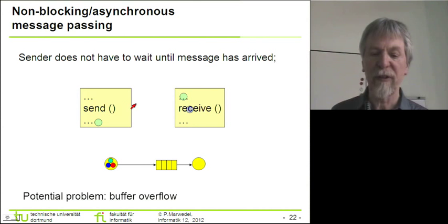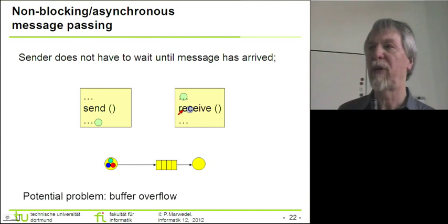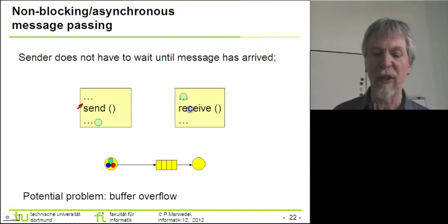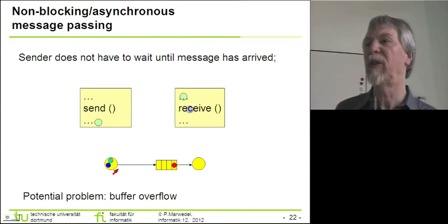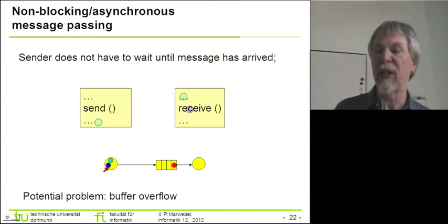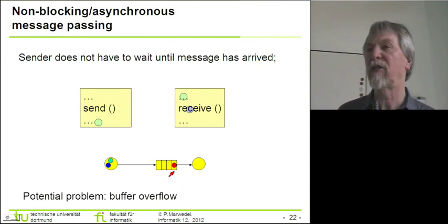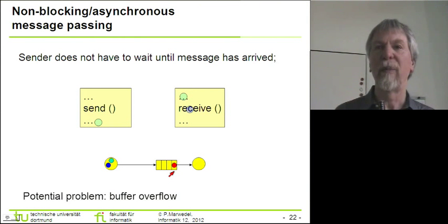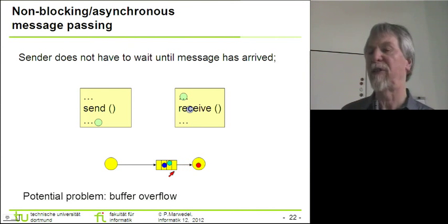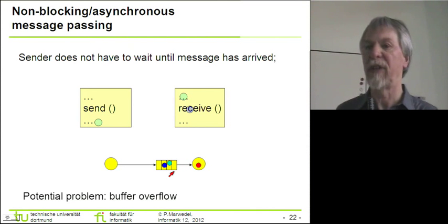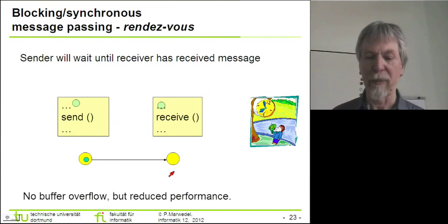If we look at this from the point of view of the corresponding information there in some kind of buffer, we see that initially this information is just sent to some buffer, which is typically implemented as a FIFO buffer, and it may happen that we store several packets of information there in the FIFO buffer before the recipient is processing the first entry there in the FIFO buffer.